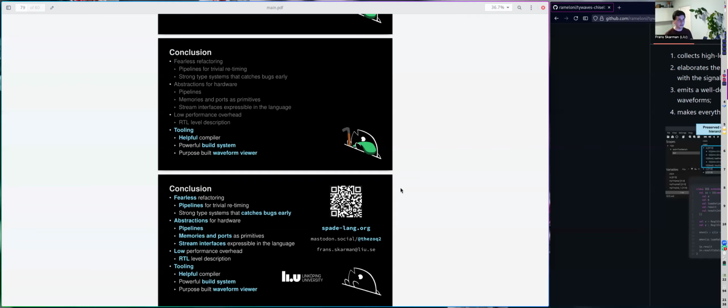So if you have Vivado where you don't have a source attribute, or maybe it does, I'm not sure, if you get a log file, you can just run that command on that log file and translate all the Verilog lines that it spit out back into the things you actually care about in the high-level HDL. Great.